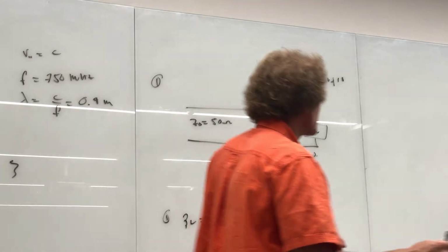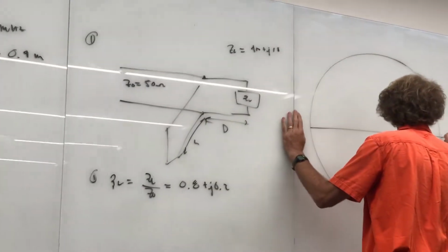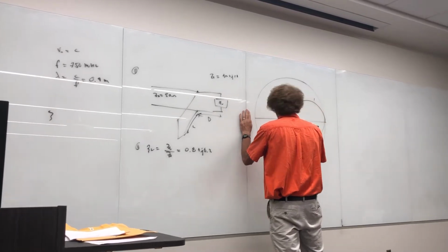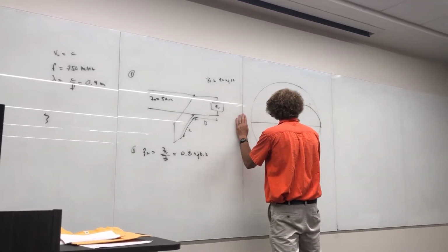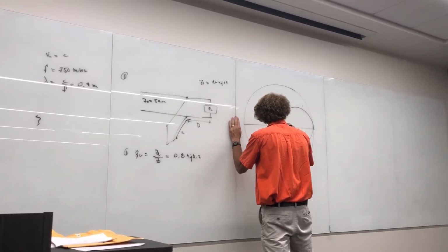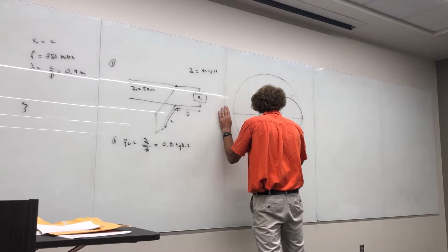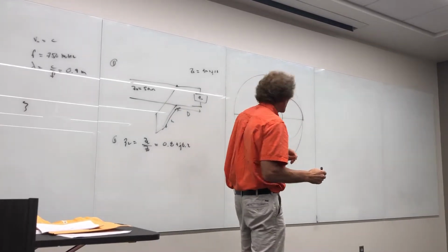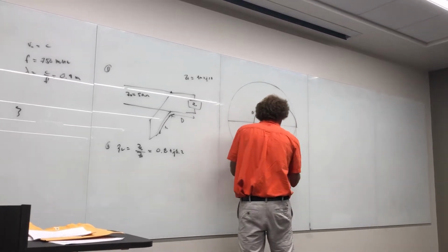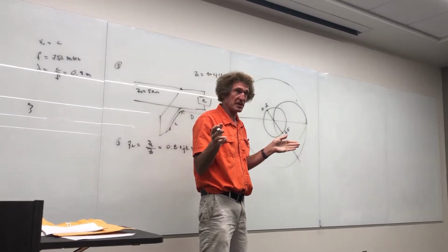All right. Now on the Smith chart, and I'm going to just scratch one up here. That's the one circle. That point, 0.8 plus J 0.2 is about here. So this would be ZL and 0.1. So I expected to see something like this, and a straight line through here. The next point, 2, is YL here, and that's the point you move from. All right? Because remember, these are in parallel or shunts, so we're working in the Y admittance domain.